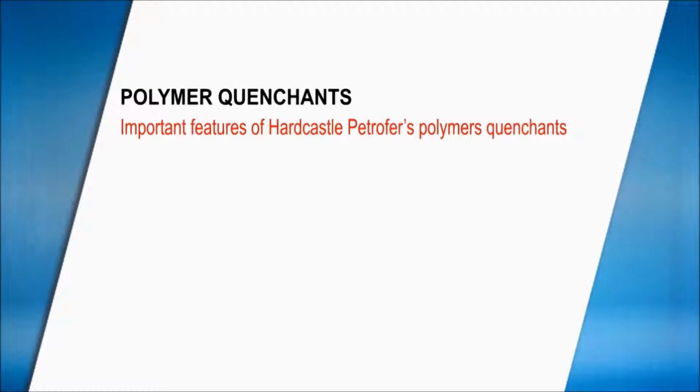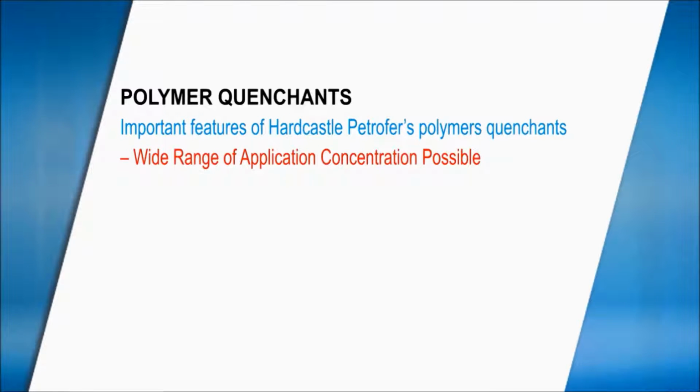HARDCASTLE Petrofer has rich experience of formulating and manufacturing polymer quenchants. The wide range of polymer quenchants available provides users the choice of options to suit their performance requirements. These polymer quenchants can be used in a wide range of concentrations in water. This property provides users with the flexibility to use the same polymer for quenching a variety of steel grades and also for use in induction hardening as well as tank quenching applications.